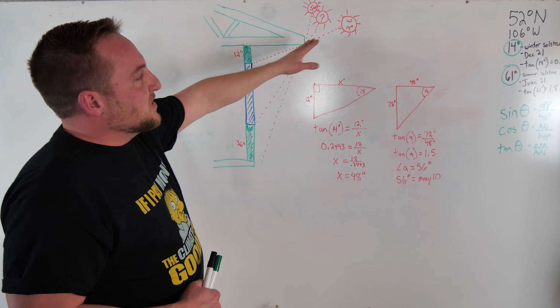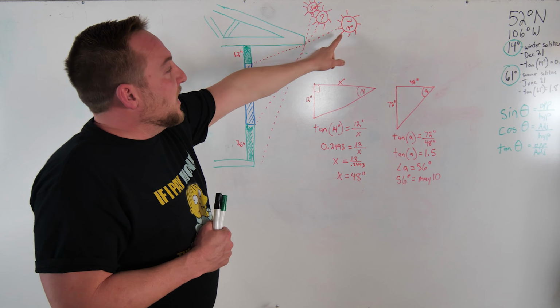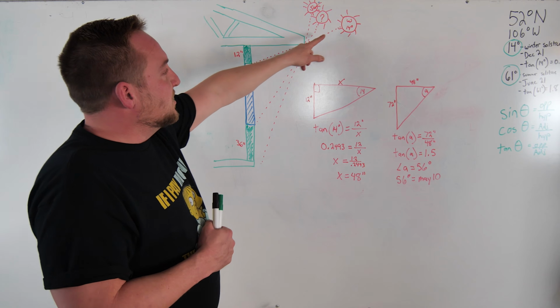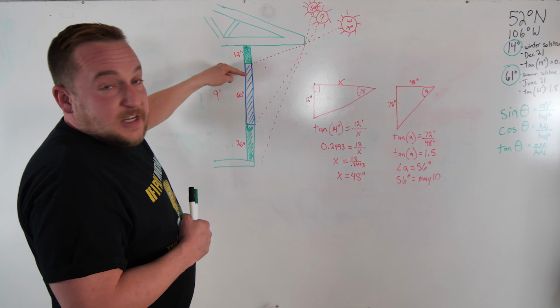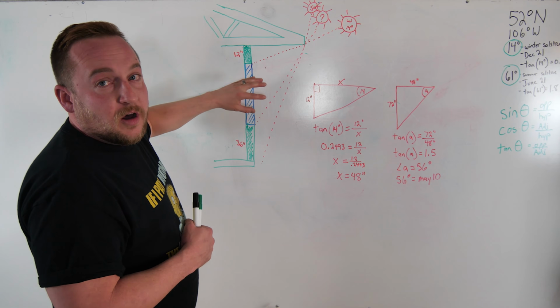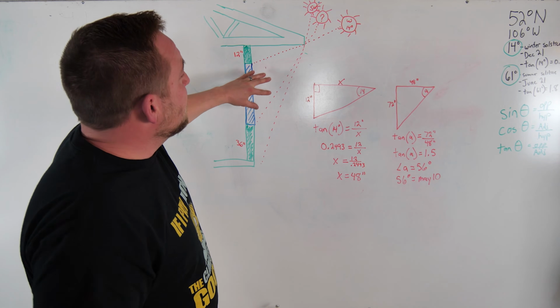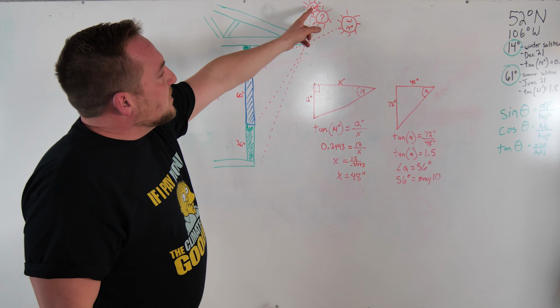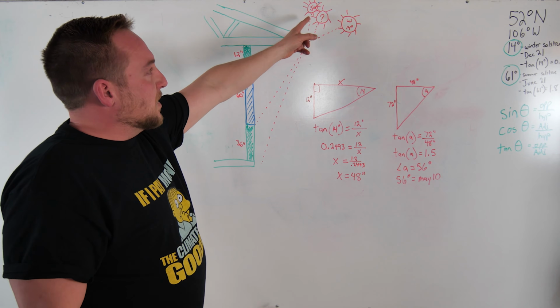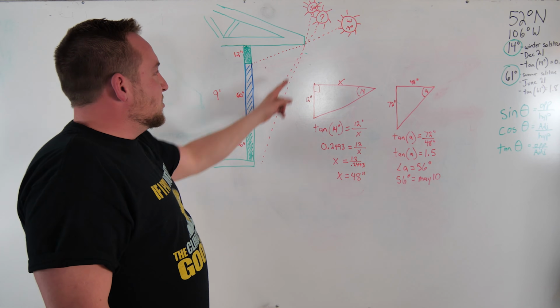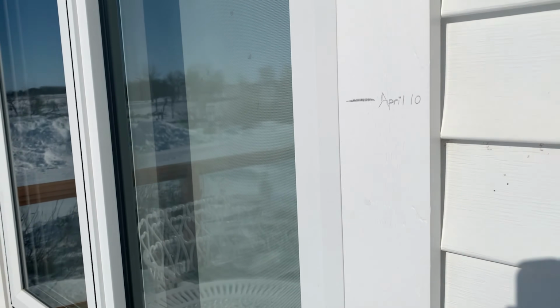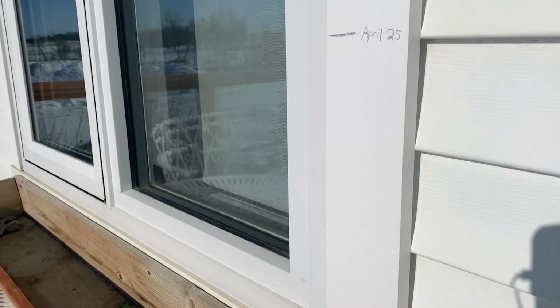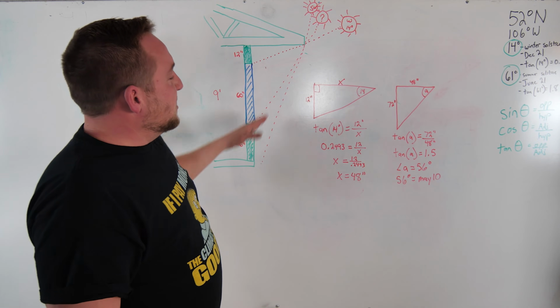And here is an example of the sun in my house. At 14 degrees, the sun's coming in, and I'm getting full sun in my entire window on the south of my building. Here's the summer sun, the summer solstice. It's not even touching my building, but I also calculated at what day is my window completely shaded from any sun coming in.